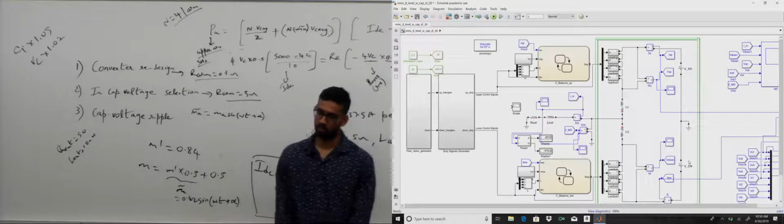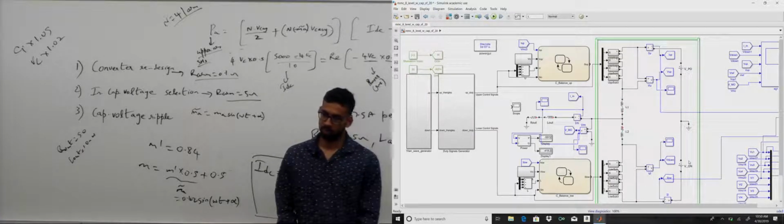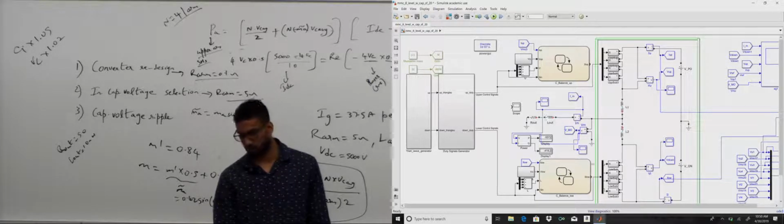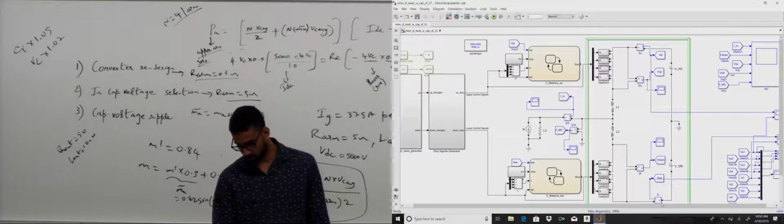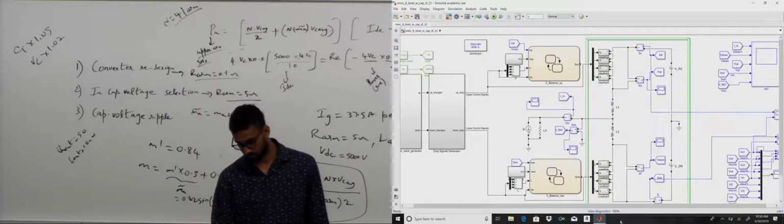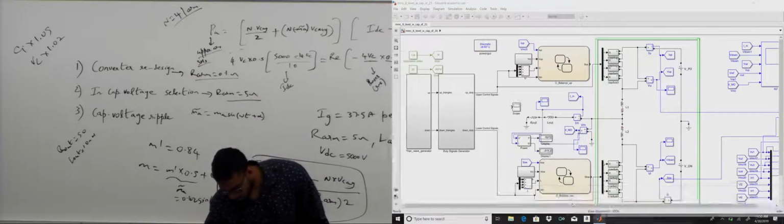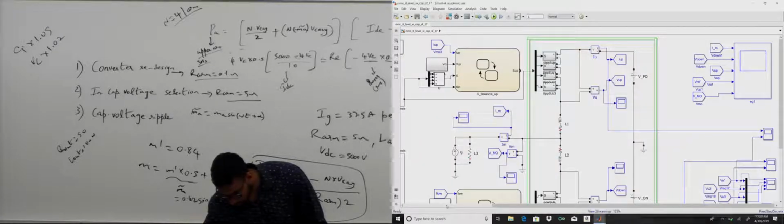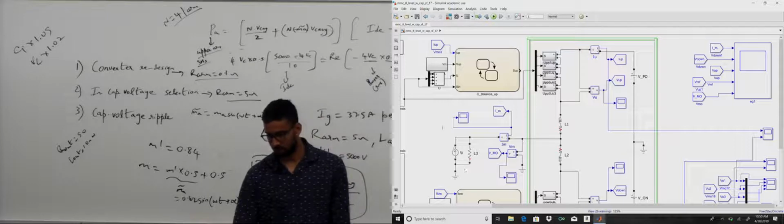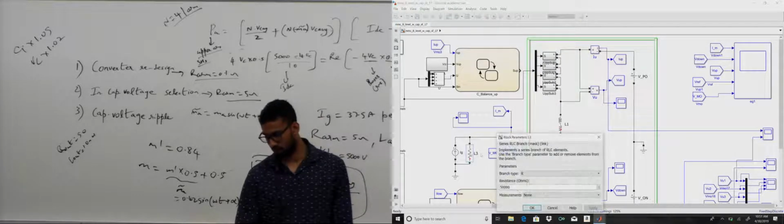What else should we do? Yeah, so for the first question, you remove the AC source and connect R out and L out. For the second question, what will you do? You do this. Remove R out, L out, AC source, everything. Just connect an AC current source, like this, feeding into the MMC and the large resistor in parallel with it, say 500,000 ohms.